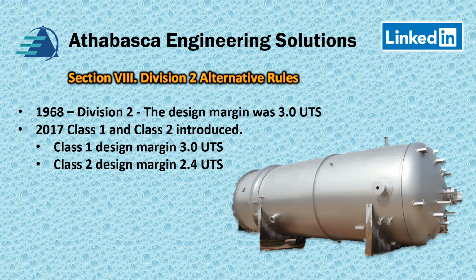So in 2017, there was a big change to add more flexibility. Class 1 and Class 2 were introduced. Class 1 allowed for a margin of 3, so basically no change, except there were a few details you have to be careful of. And for Class 2, they allowed an even bigger drop to 2.4 of the tensile.